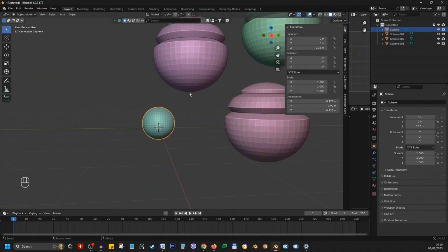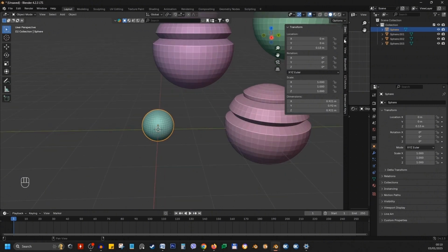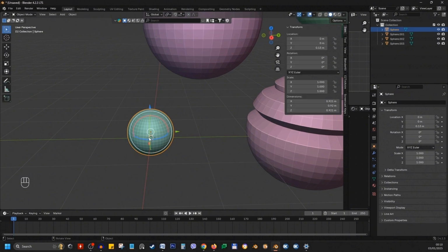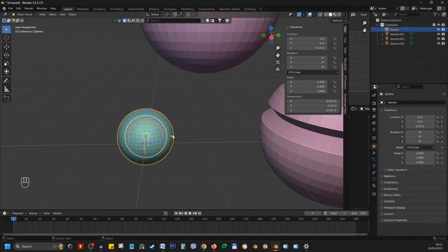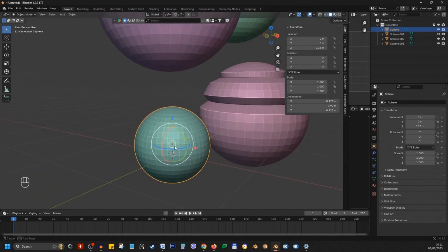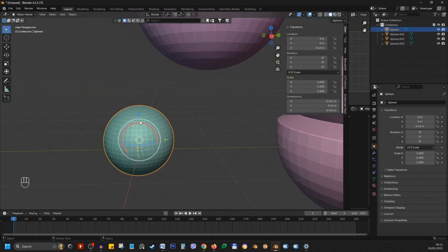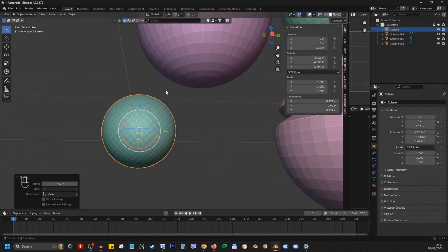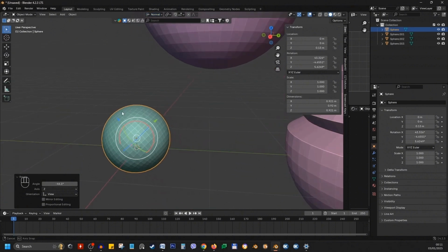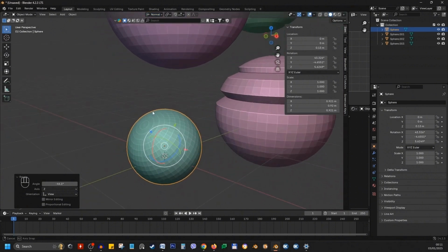We can move or rotate objects in Blender in different ways. Let's turn on the move gizmo and the rotate gizmo. I don't really use the rotate gizmo, but the move gizmo is often quite useful, as it always shows us the orientation of the object. So if I select it, hit R, and rotate it, the arrows are showing the world orientation, because we have global selected. If I select normal, now we're seeing the object's normal directions.